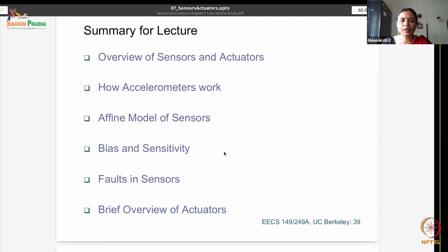To start with, what do you do in polling? You basically have a main loop which periodically, at a frequency or period that you design based on several other parameters, reads input output data. If an output needs to be produced, it will produce it. If an input is ready, it will read it and convert it. So here is how one polling works.